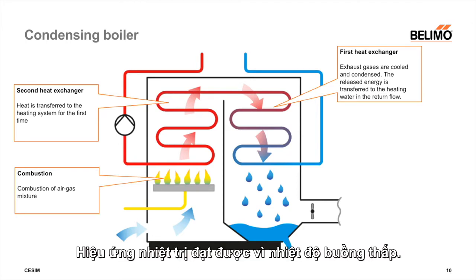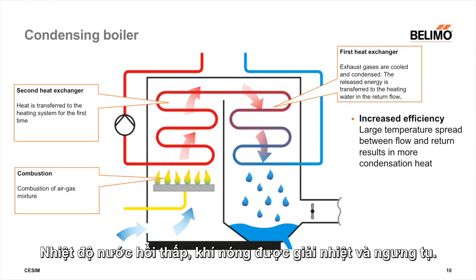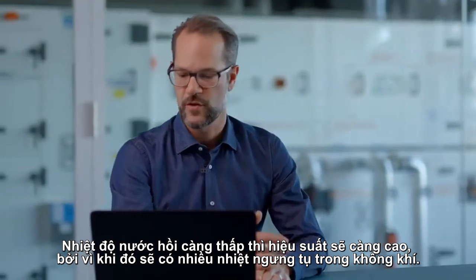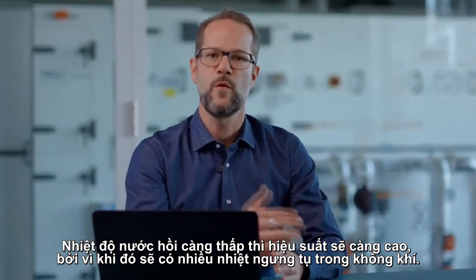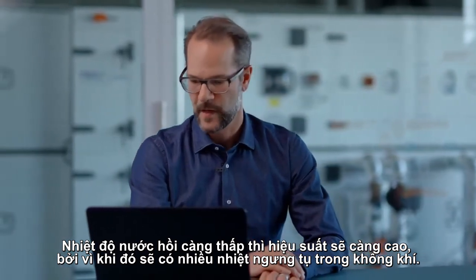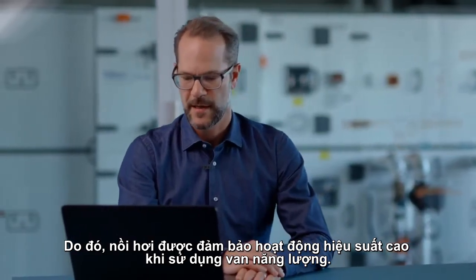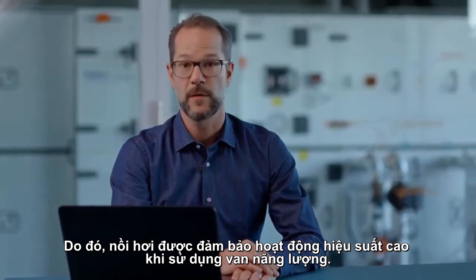The calorific value effect is achieved by low system temperatures. Due to the low return temperature, the gas is cooled and condensed. The lower the return temperature is, the better the efficiency, because I have more condensation heat in the gas. So therefore, the energy valve can ensure that this efficiency is guaranteed for condensing boilers.